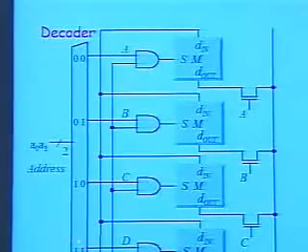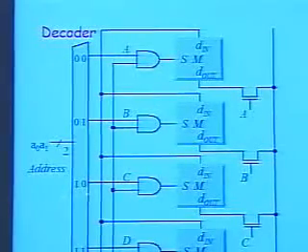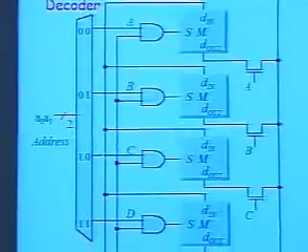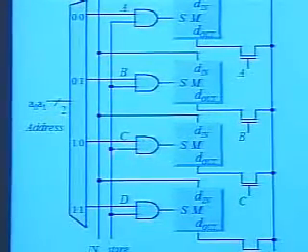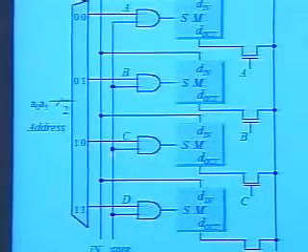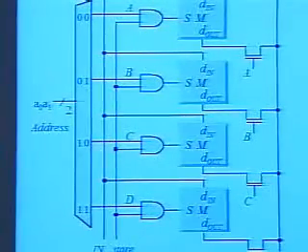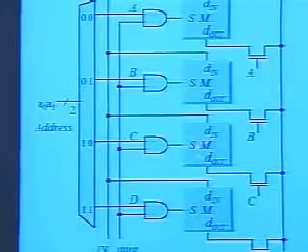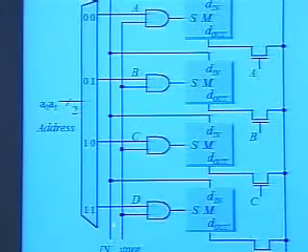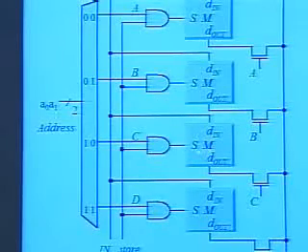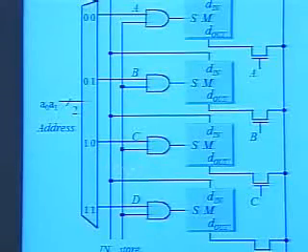So if, for example, we have a 1, 0, the only AND input that is going to be high is going to be this one. And that means the only cell that will look at the input when the store comes up is going to be this one here. So at that point, it will store whatever is on the input, because that's an AND operation.